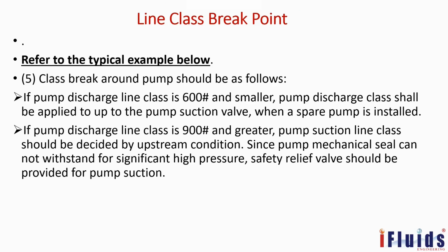Class break point around a pump shall be as follows. There may be different types of pumps, but the line breaking for the pump has 2 points. If the pump discharge line class is 600 and smaller, the pump discharge class shall be applied to the suction valve also when a spare pump is installed. If the pump discharge line is 900 and greater, the pump suction line class should be decided by the upstream condition. It should not be the same 900.